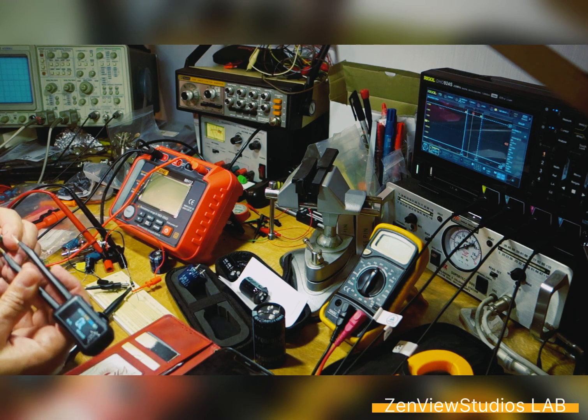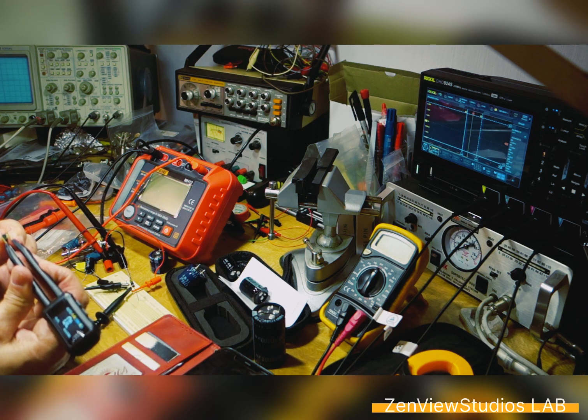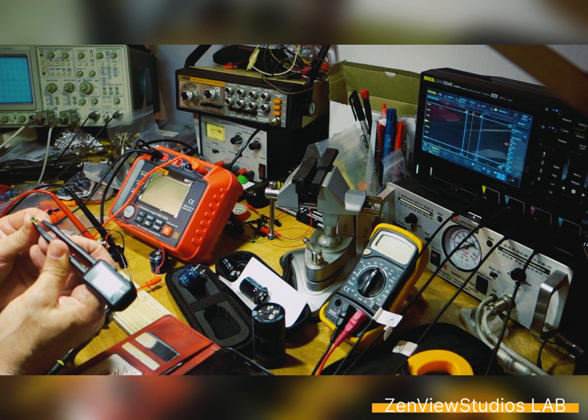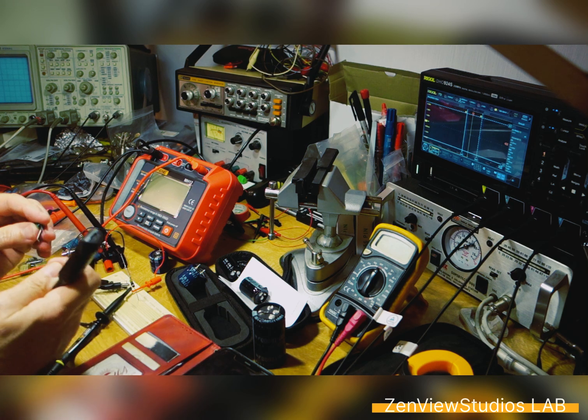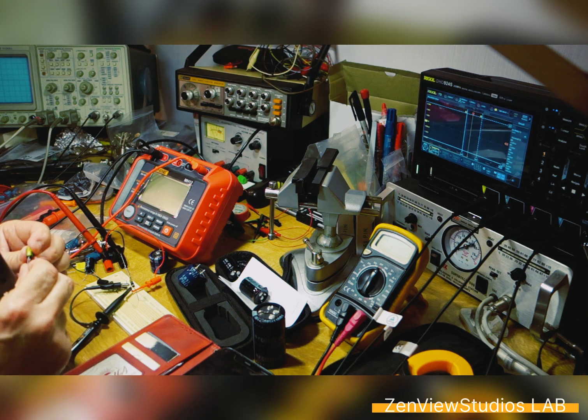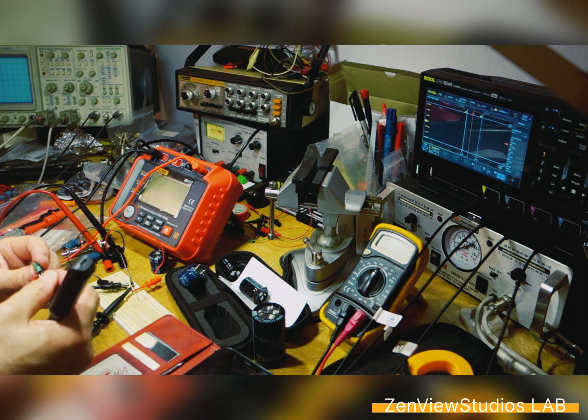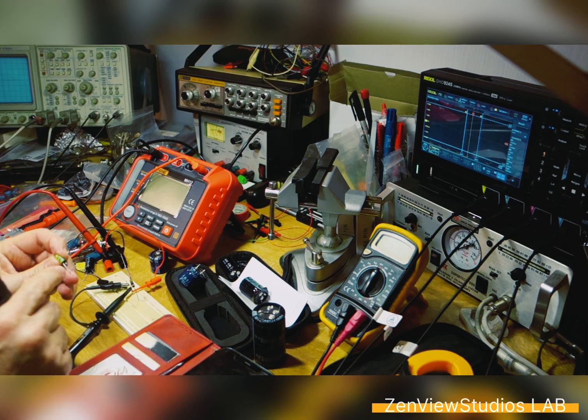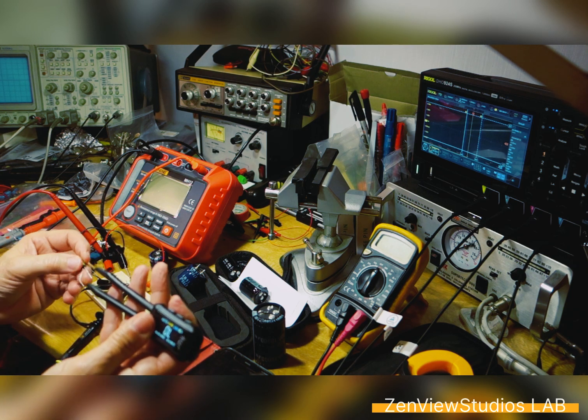The capacitance is not exact anyhow, you have a tolerance for your capacitors. So here this one, which is probably much closer to reality, is 99.38 microfarad at 100 hertz. Now you have to check also that the reactance is not interfering with that, namely because of the capacitance and the frequency you're testing at.